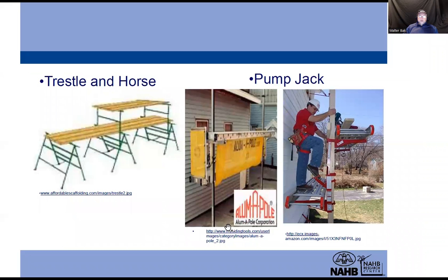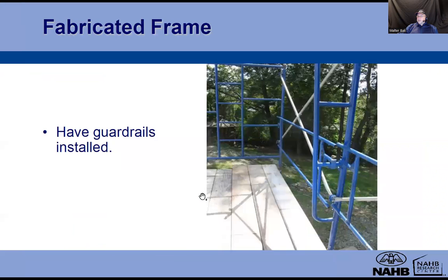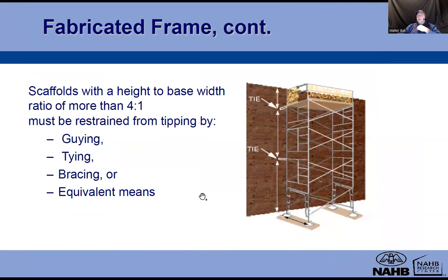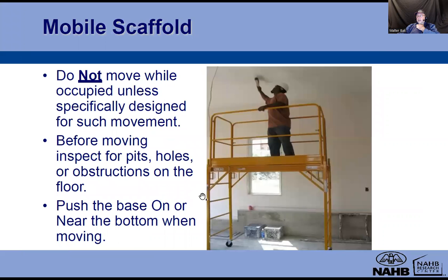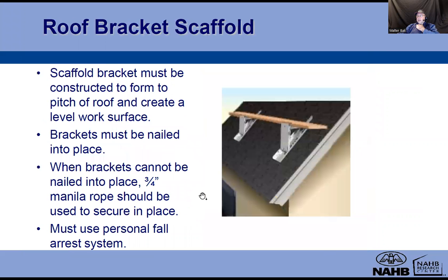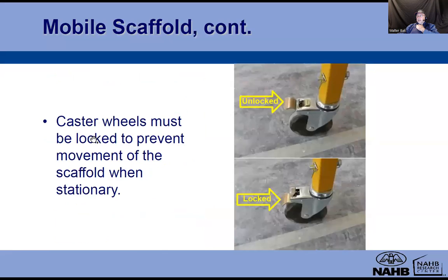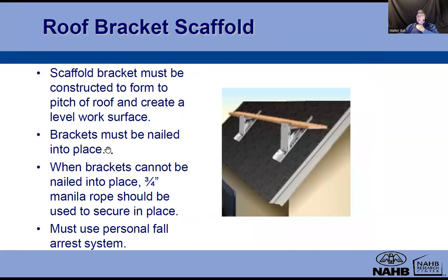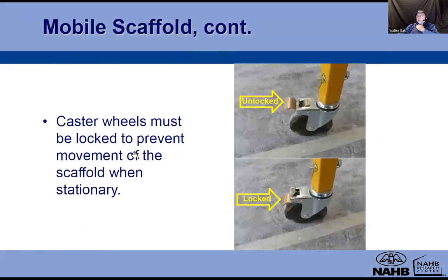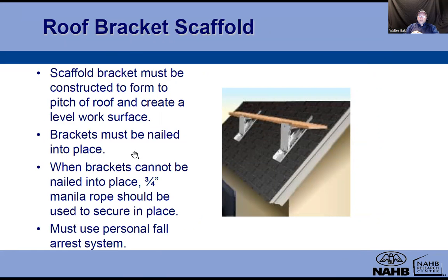Whenever you use people working on the scissor lifts or boom lifts, for sure you're going to have those harnesses. If a safety inspector walks by and sees you without those harnesses, you might get into trouble. And always check, because those laws change what you actually need to have as a personal fall arrest system.